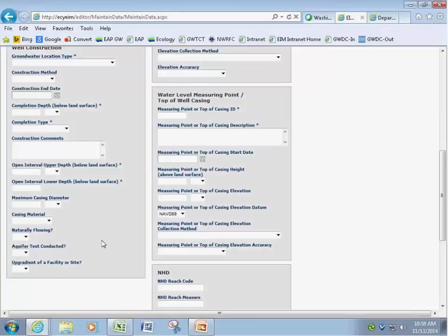And if you start thinking kind of big picture, I could go into the search and say, show me only wells across the entire central region of Washington that have been flagged as up-gradient. And compiled, synthesized together, I might be able to get a better understanding of what a background or an ambient condition is for a particular water quality parameter that I'm interested in regulating against.